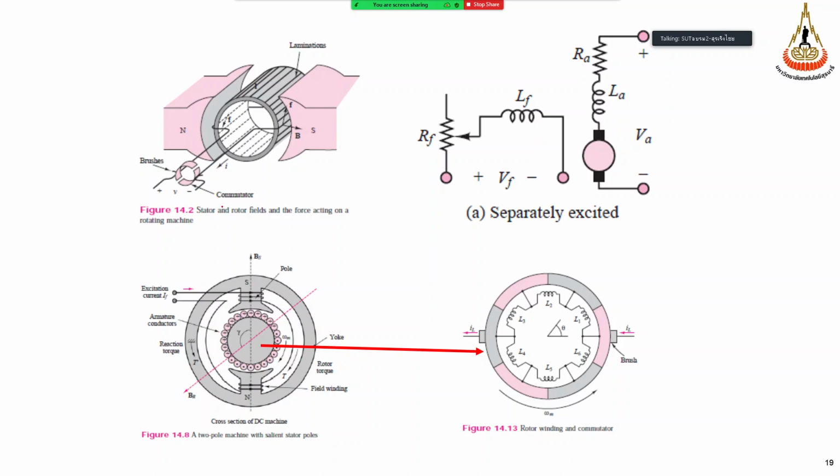we need a device known as brush and commutator. Commutator is the ring, right? A conductor in the ring shape, and the brush, usually made of carbon, touches this ring, and this ring can move. During moving, the electricity can flow through this brush. We can have the electrical connection to the moving part of the machine, because this is the carbon brush and slip ring or commutator here.